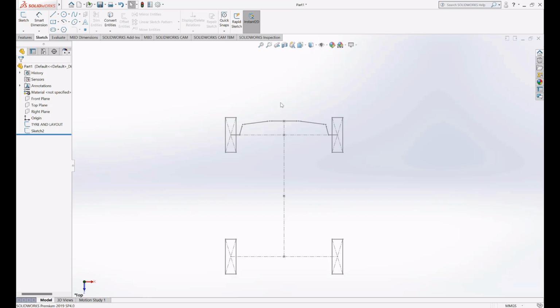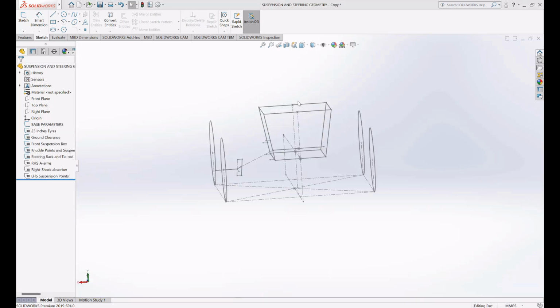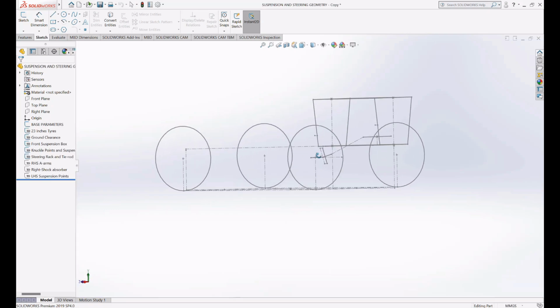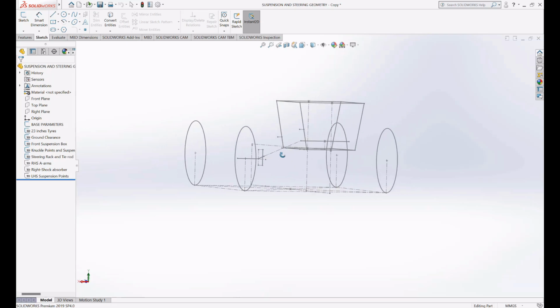The more anti-Ackerman percentage you have, the sharper the vehicle will be able to turn, but there are high chances that it will slide, because anti-Ackerman steering geometry promotes the ability of the vehicle to slide when turning. If you compare this with the 3D, it will be like this. In the next video, I will try to make the steering geometry in 3D.